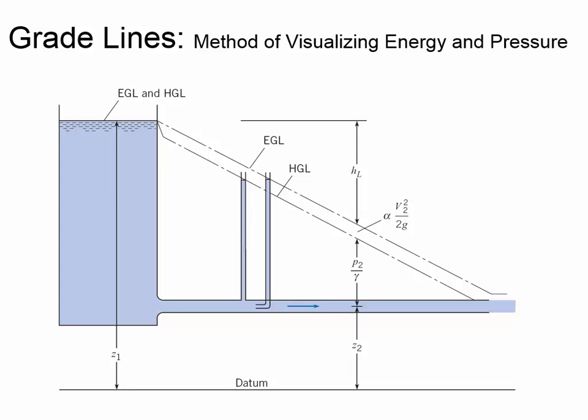The velocity is being transferred into additional pressure inside of that tube, because you'll notice it's a different kind of an opening. The opening on the left isn't intercepting any of the velocity, but the opening on the right is actually facing into the flow, and so the water in the pipe is moving along. It has some velocity head, but suddenly it comes to this stagnation tube. It's an opening inside of the pipe where it's intercepting the streamline of the velocity, and so all of the energy that's tied up as velocity is exchanged into a little bit of additional pressure, and that pushes the water up just a little bit higher. And so that's the physical interpretation of the energy grade line, is how high the water will go based on the elevation, pressure, and then also taking the energy that exists as velocity and converting that into some additional head inside of the tube.